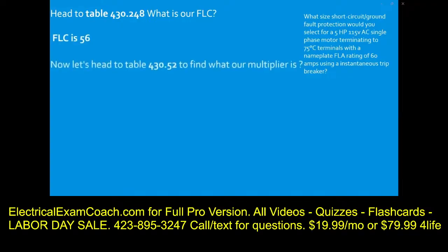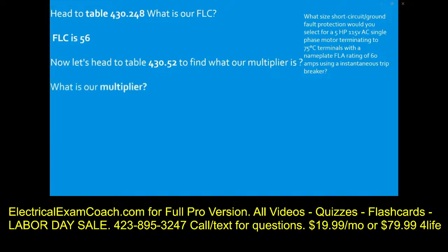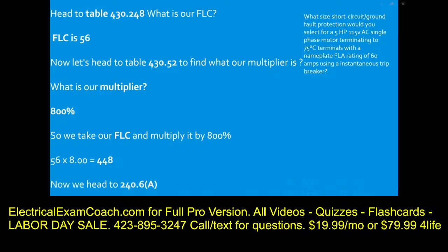Now we head to table 430.52 and find our multiplier, starting on the left-hand side, finding single phase, then coming across to the type of device. In this case, we're going to find that our multiplier is 800%. So we take our FLC, 56 multiplied by 8, and that's going to give us 448 amps to size our device by. Now we're going to head to table 240.6(A). We're going to select the next size up, and we're going to select a 450 amp overcurrent device. Now, just for fun, we're going to take this same question and we're going to size the conductors.